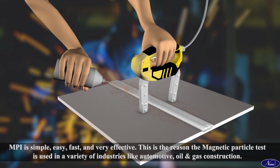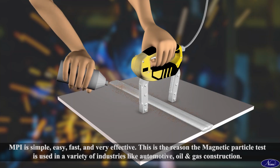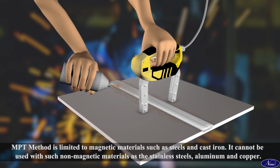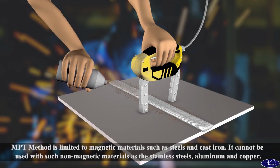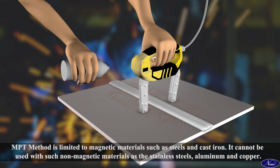This is the reason the magnetic particle test is used in a variety of industries like automotive, oil and gas, and construction. The MPT method is limited to magnetic materials such as steels and cast iron. It cannot be used with non-magnetic materials such as stainless steels, aluminum, and copper.